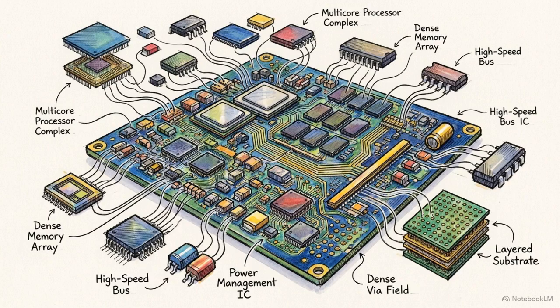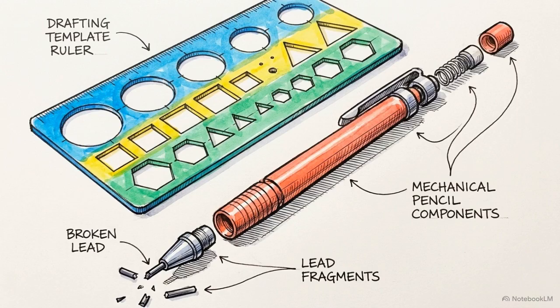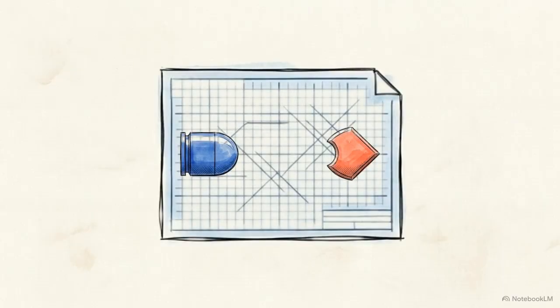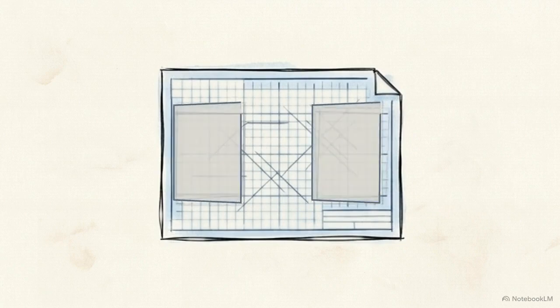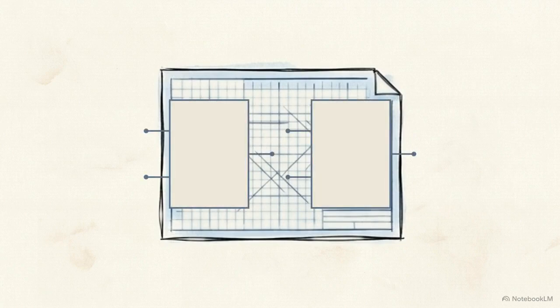As digital logic grew exponentially more complex through the 1970s, custom shapes reached their operational limit. Designing a unique silhouette for every new, highly specialized integrated circuit became impossible. The industry began migrating away from the ANSI Y32.14 standard that maintained these shapes, seeking a more systematic approach. The solution was the IEC 60617 mandate, which forced all logic gates into a standardized rectangular block footprint.